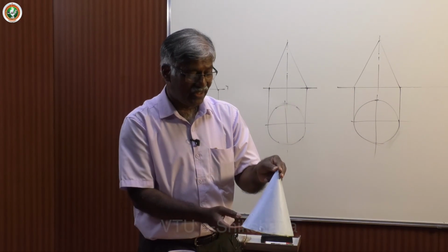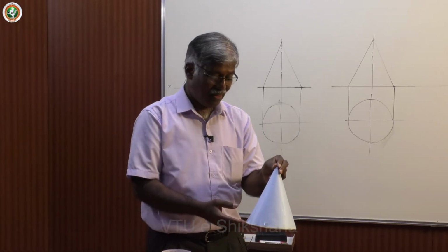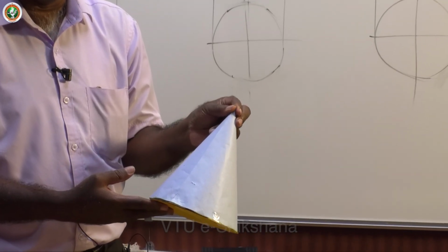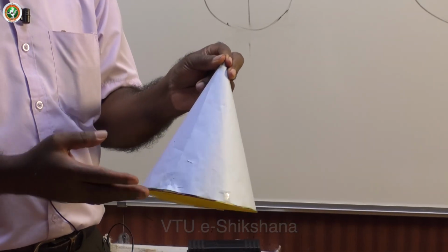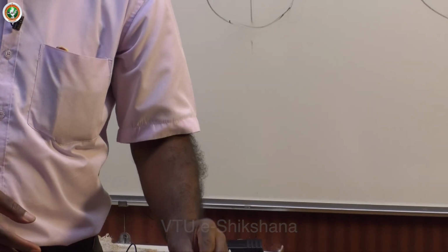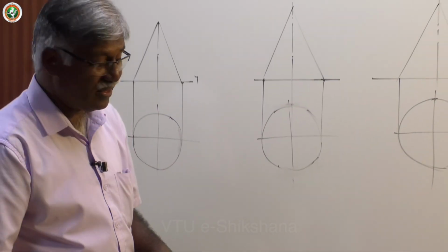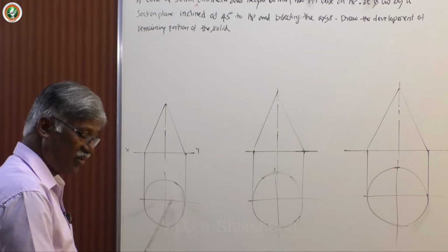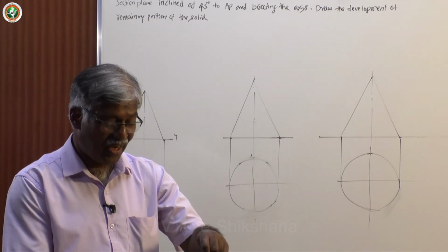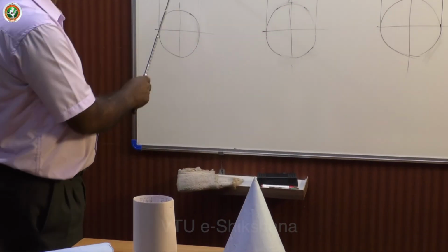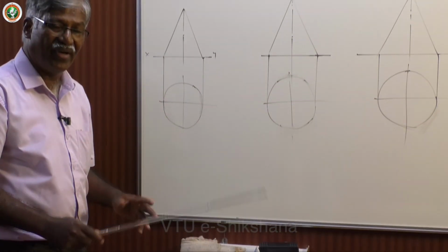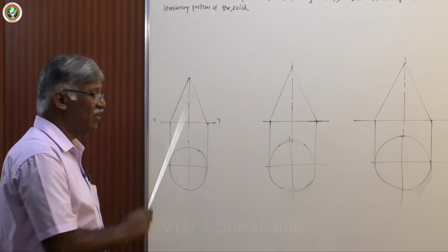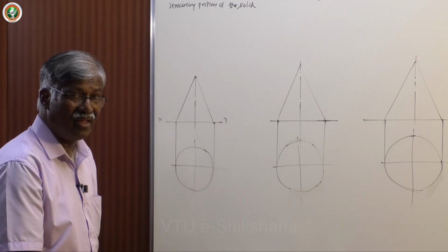Now you know in solids as well as the laminae, we learned how to get the circular laminae, and in solids how to draw the projection of the top view and front view. Here the same thing I have identified. Assume that I have a circle as the top view when you keep it on the ground, and the front view is actually an isosceles triangle. In a particular case it is equilateral, when the base side is equal to the sides of the isosceles triangle.